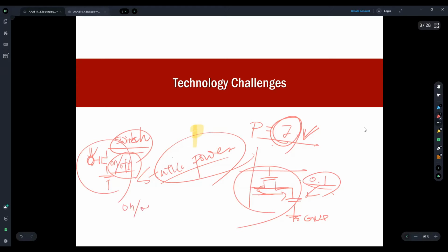So we can control on and off with this CMOS transistor with this gate voltage level, but if the CMOS transistor is not entirely closed, then electric current flows from VDD to the ground. So it consumes electric power. And in recent devices, the CMOS transistor size is very small, which means that we cannot entirely close this circuit. So the electric charge passes through this transistor, even though this transistor is turned off.